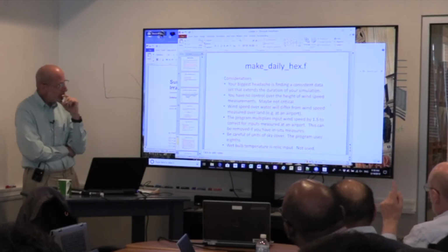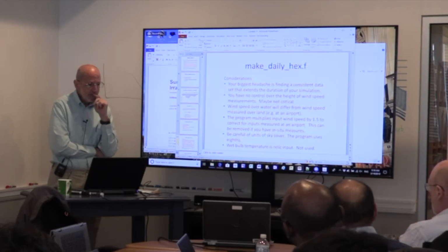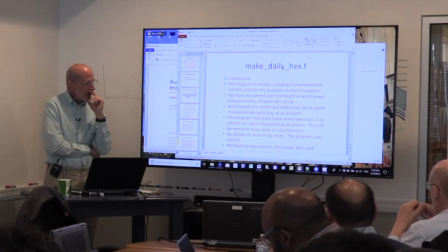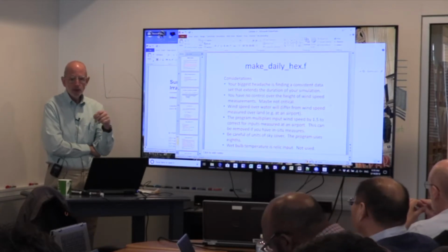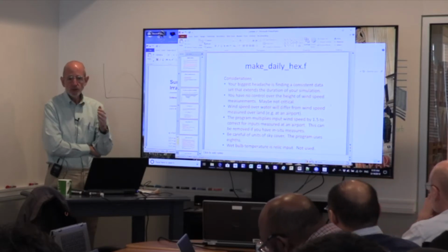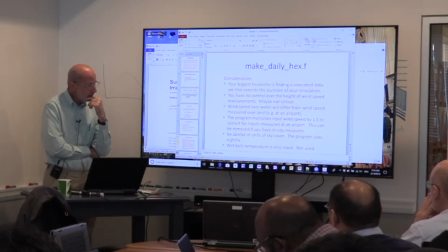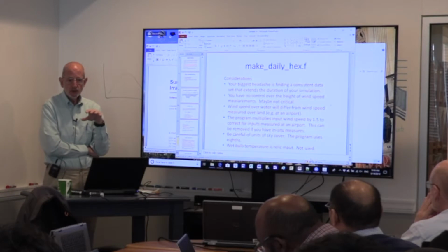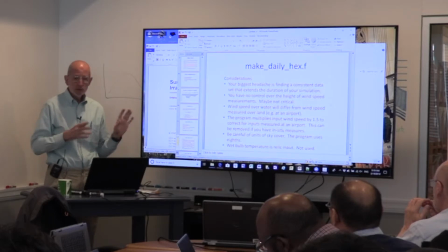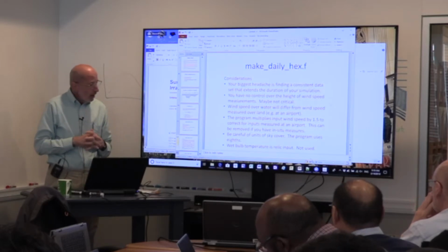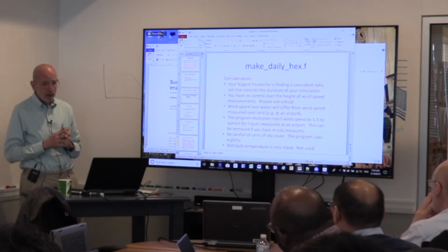One other question. Whatever station you pick, this MET file that you're creating applies to the entire system. Is that correct? Right. Okay. Yeah, we had some questions about that. In the hydrodynamic model, wind is really crucial to computing surface shear stress, and I think the hydrodynamic people actually get MET data from many different stations and interpolate it and apply it to each individual cell in the grid. We don't go to that level of detail. We can't really go to that level of detail. You could average a bunch of stations if you liked.